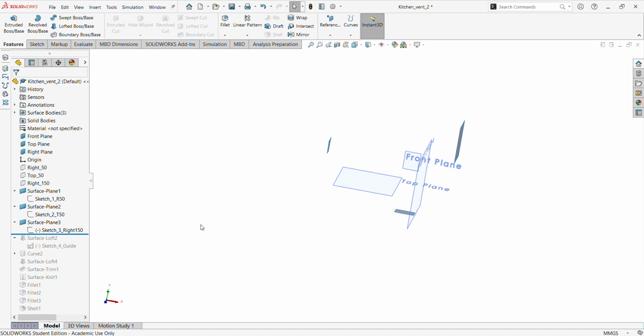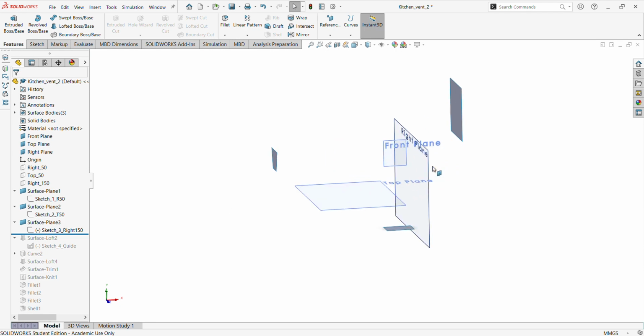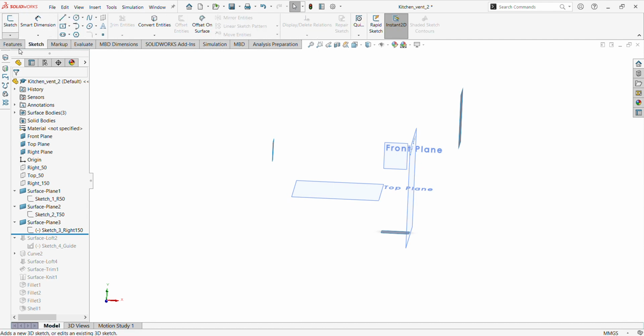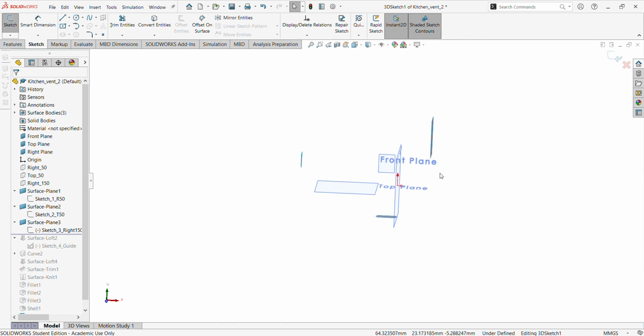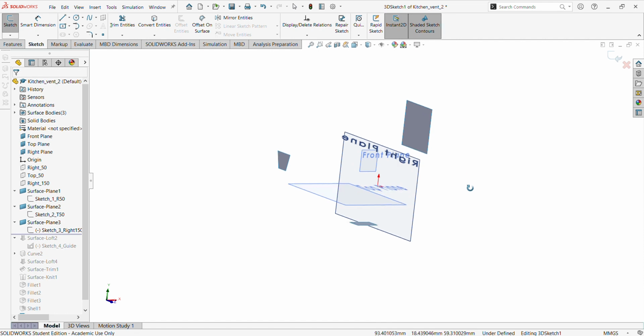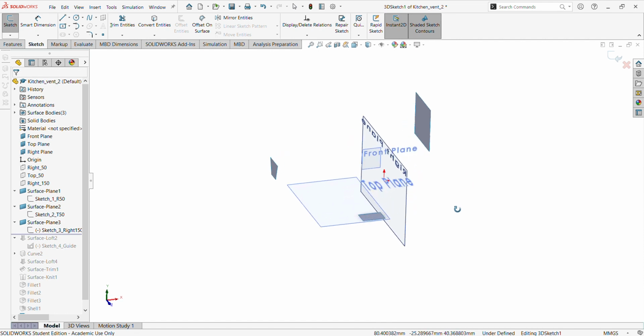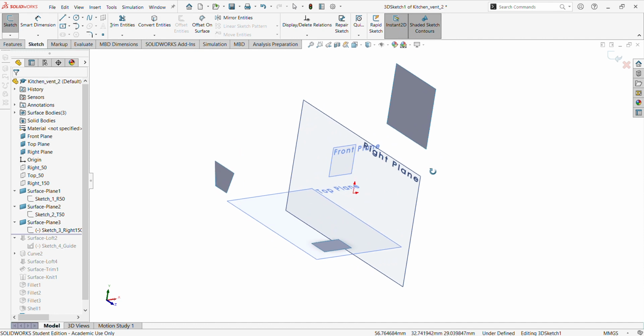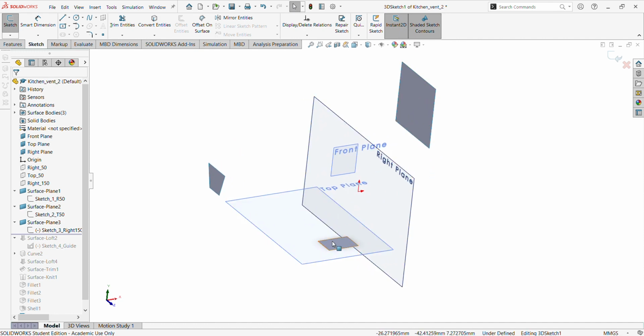So now we have three faces. Then we have to do a 3D drawing, and I have to explain because I already have that sketch on it. You go to a sketch and take a 3D sketch, because it's only the 3D sketch that can give you the guide curve that will fit in. You can also do it in a 2D sketch, but I will explain why 2D sketch can't really work here. For this guide curve to be effective and give us exactly the curve we want, we have to do a pierce relationship at this point and draw it up to doing a pierce relationship at this point.